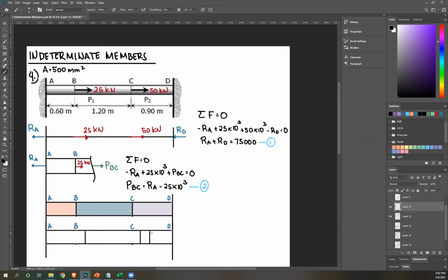Okay. So now, this is your final segment B, right? And then B. And if you've noticed, the total deformation of B is this much, right? And this portion is a deformation due to this 25 kilonewton force, right? So that's basically deformation of BC, okay? Or deformation, how much this moved.